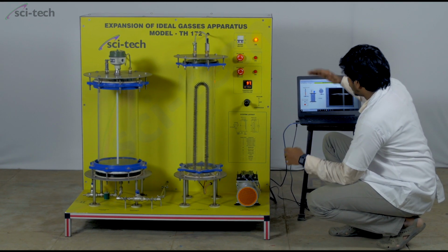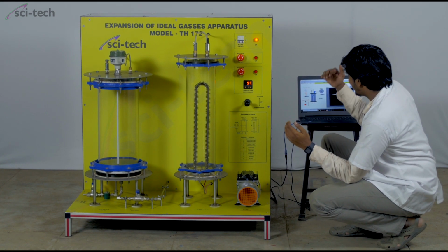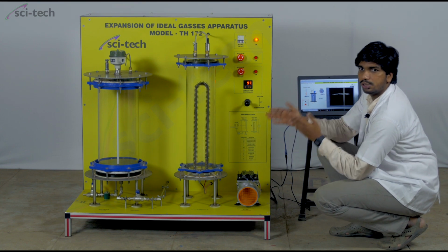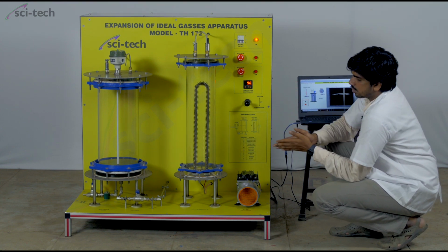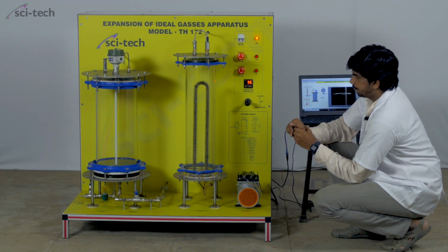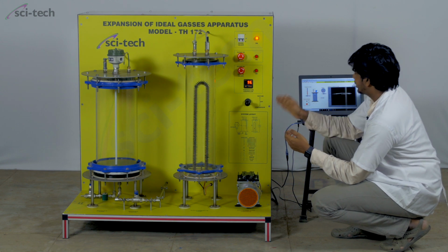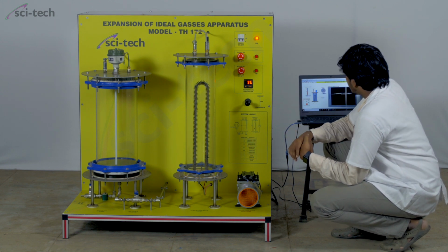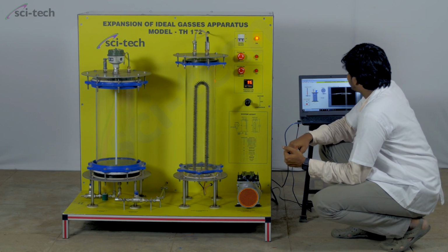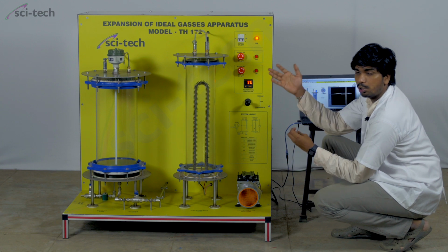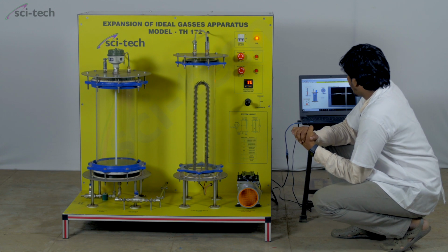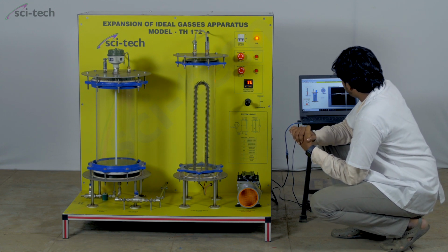As you can see, the graph is going down linearly, because whenever the temperature is decreasing, pressure is also decreasing. Gay-Lussac's law states that the volume inside should remain constant, which it already is, and as the temperature decreases, in the same way our pressure is decreasing. Now our temperature is around 103 degrees Celsius in our application and the pressure is 0.092. So from 0.099 it has come to 0.092, then 102 degrees Celsius, 0.097.